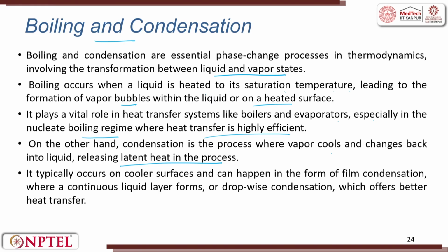It typically occurs on cooler surfaces and can happen in the form of film condensation, where a continuous liquid layer forms. So, what happens is, when you have very high relative humidity and you have a pipe through which you are passing cold air, what happens?